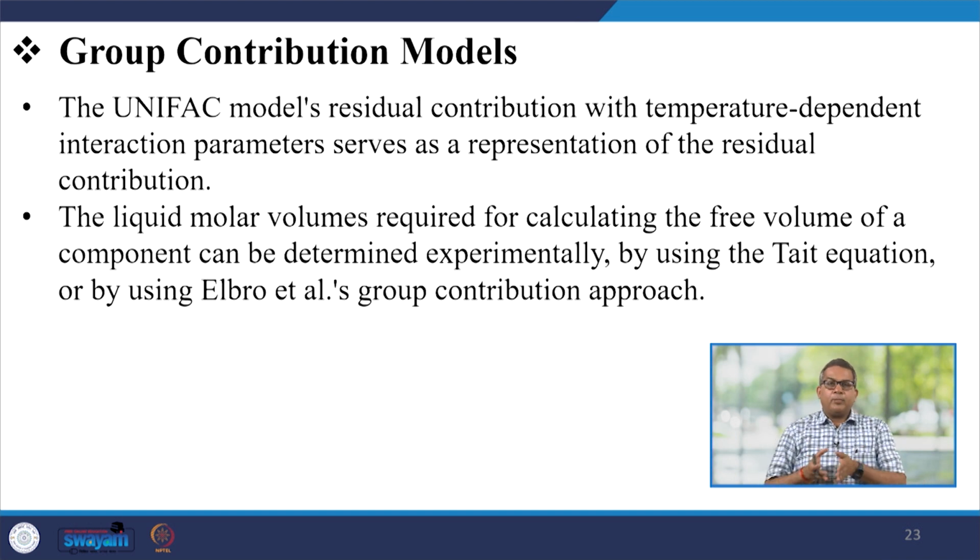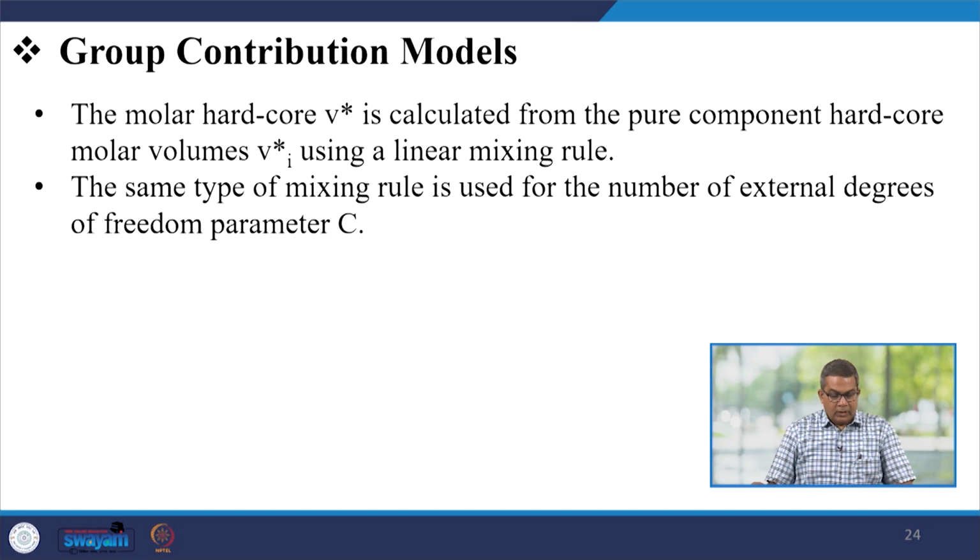Now, the liquid molar volume is required for calculating the free volume of a component. This can be determined experimentally by using the Tait equation or by the Elbro group contribution approach. So, the molar hardcore volume is calculated from the pure component hardcore molar volume using the linear mixing rule. Now, what is this linear mixing rule?